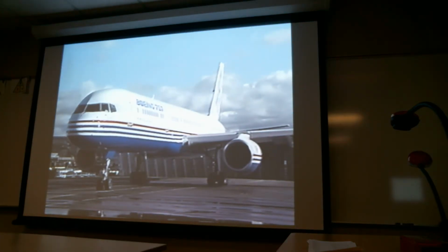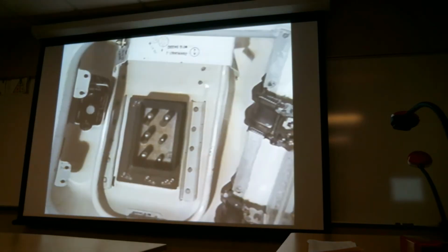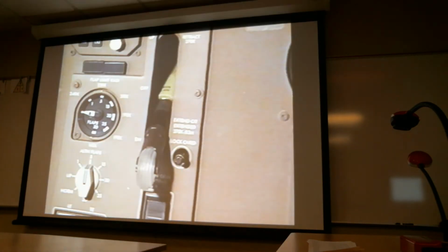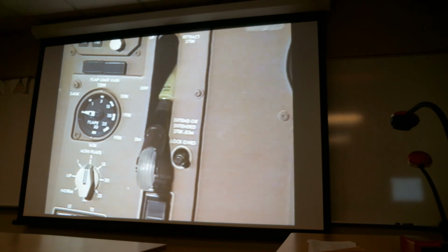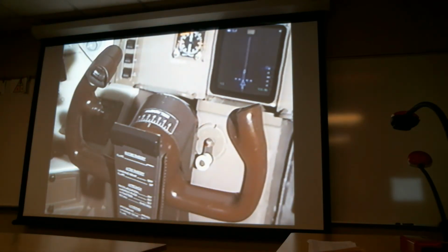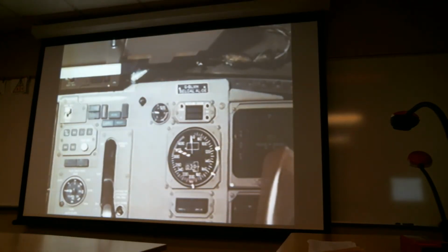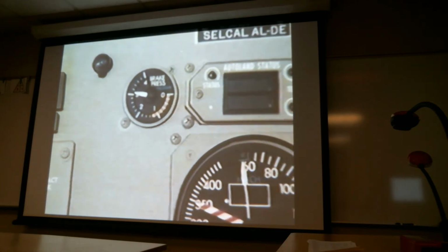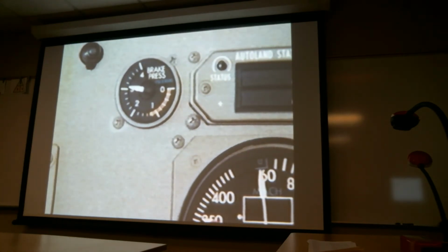To service the hydraulic system, the aircraft must be in the following configuration: electrical power provided and the ground service bus energized, landing gear down and the landing gear doors closed, actuator position, steering, and flight controls at neutral. And when servicing the right system, the brake accumulator pressure gauge must read a minimum of 2,500 psi.